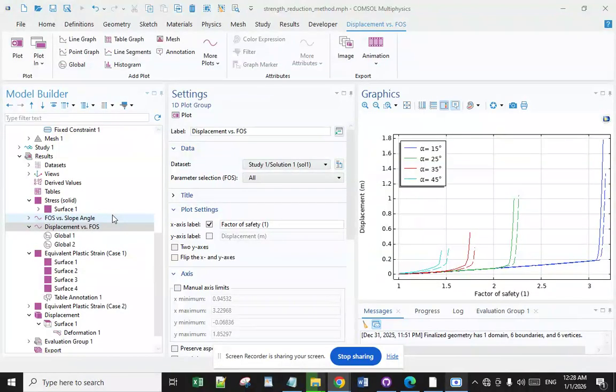The finite element method has become a primary approach for quantitatively assessing slope stability due to its modeling convenience and computational efficiency. With advancement in computer technology, FEM has gained significant attention and is now commonly used to evaluate the factor of safety as an alternative methodology, and the FEM strength reduction technique offers several notable advantages over traditional limit equilibrium and limit analysis methods.